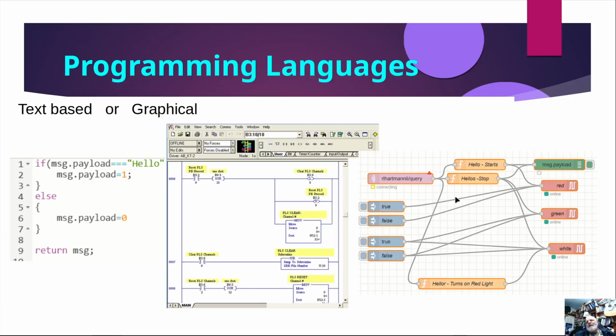And then on the right, we have a very graphical piece of code here. This is called Node-RED. And so each one of these here are nodes. And then the whole thing is called a flow, and so data will flow from a node into another node. So this node here on the left is what we call an input node, and in this case it's bringing input from across the network, and then that data is going to be passed through a function block and processed, and then it goes to an output.